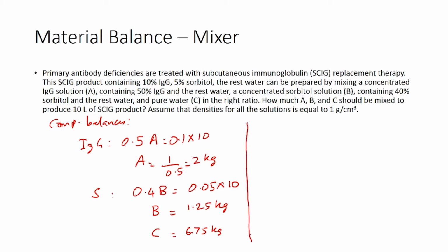So, the last slide which we looked at when we saw performing the fundamentals for engineering calculations was validating the answers we arrived at. One possible way to do it would be to use different equations and perform the calculations using a different approach. So, here what we can do is we can write a component balance for water and try to solve and see whether we get the same values. So, we can plug in these values to the water balance equation to confirm whether our answers are correct.